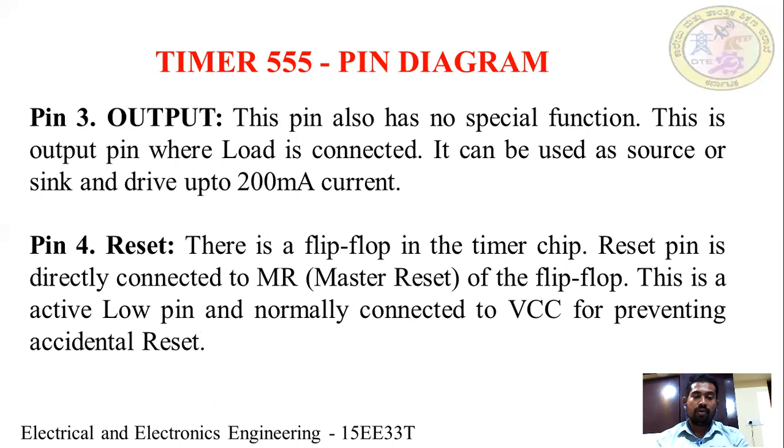So this is about pin number 3, and pin number 4 is all about reset. There is a reset button meant for the flip flop in the timer chip. The reset pin is directly connected to MR, the master reset of the flip flop. This is an active low pin and is normally connected to VCC to prevent accidental reset. If we suddenly need to reset, we can use pin number 4.